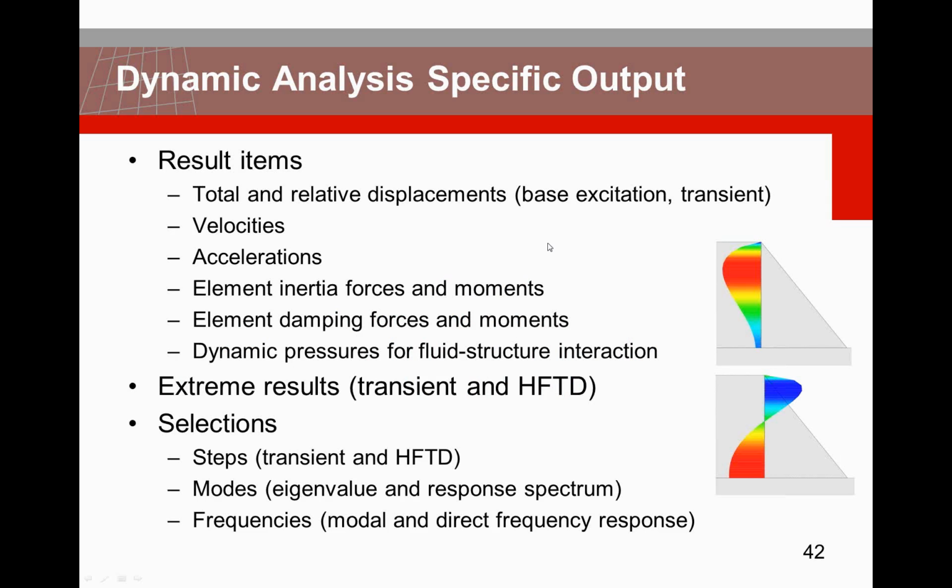Then we are going to end this presentation with some dynamic specific output items. These are, for the transient and dynamic analysis, the relative and total displacements. The frequency analysis only gives relative displacements. Velocities and accelerations can be seen. It is possible to calculate the element inertia forces and moments, the damping forces and moments, and for fluid structure interactions it is also possible to display the dynamic pressures, as you can see, for instance, in the example here to the right.